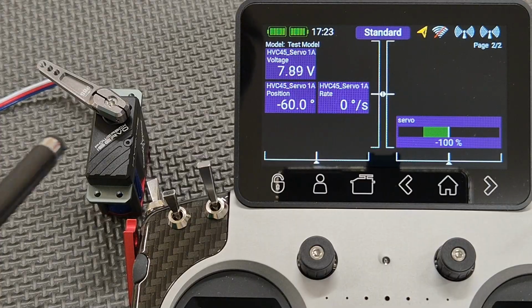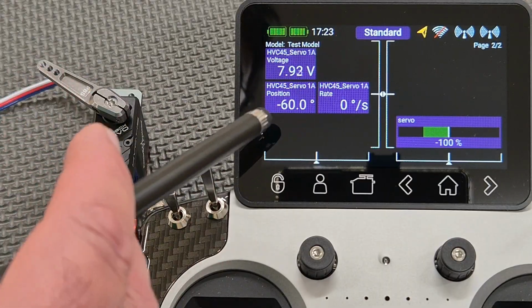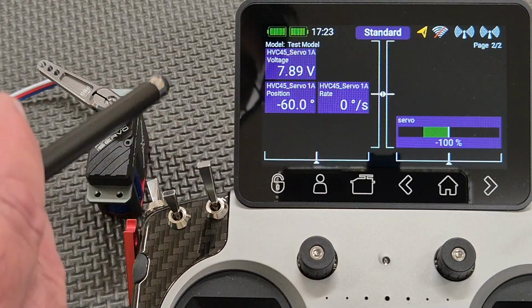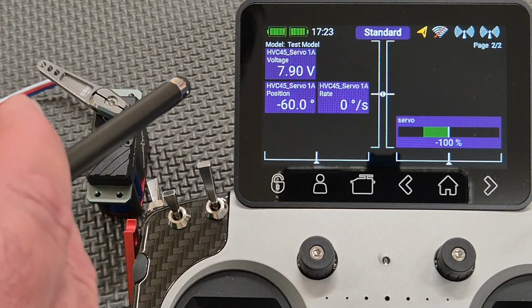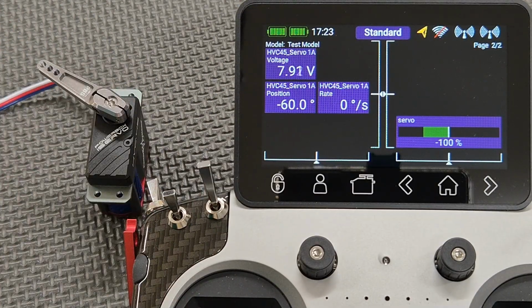A lot of the times, I don't bother with displaying a lot of these telemetry widgets for the servos, for instance. So I'll refer to them later at the end of the flight when I download the log for that flight, and then have a look at the actual log file and those parameters. So again, you don't need to have a widget displayed.